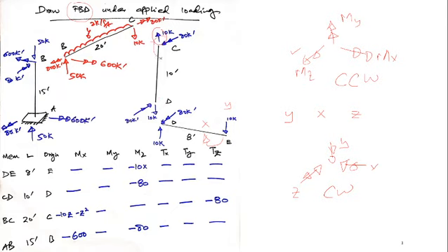Again, I have to balance this joint C. This joint C should be balanced, so I have balanced it here. This is an upward 10 kip, so I have applied a downward 10 kip, and this is anti-clockwise 80 kip foot, so I have applied 80 kip foot clockwise. You should know that this is a clockwise moment here.